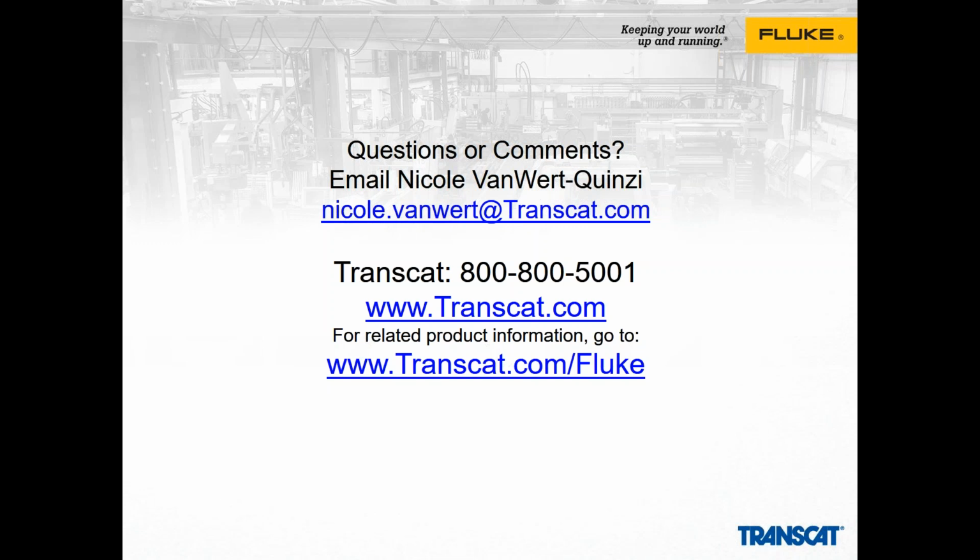If the dip occurs for too long, and the amount of time depends on the quality of the equipment, you will start to lose function, because there's no voltage there and no way to charge up the capacitance inside the equipment that does the conversion. So that's how voltage dips work.